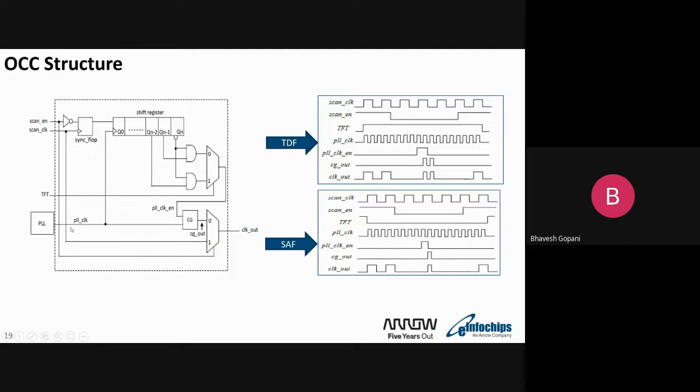In our design, when I'm saying TDF, I'm talking about top level. There are many OCCs in our design, not only one OCC. Based on the number of clocks, we have a number of OCCs. Let's say my design has 10 separate clocks. Then I need 10 OCCs for the different frequencies. I can't use a single OCC. So OCC placement is also important from a DFT consideration.